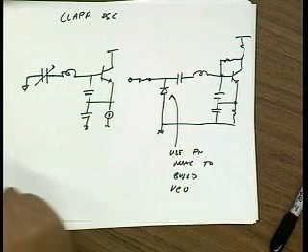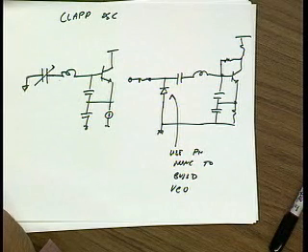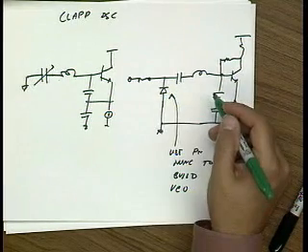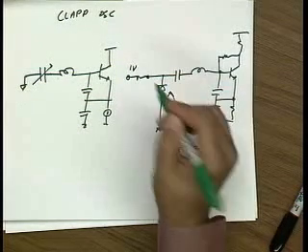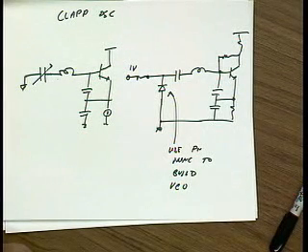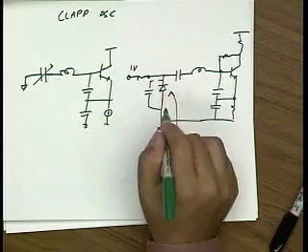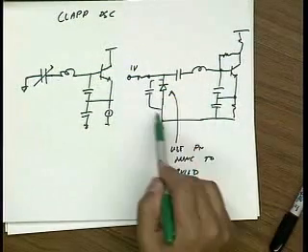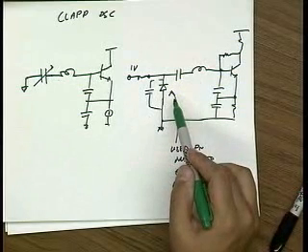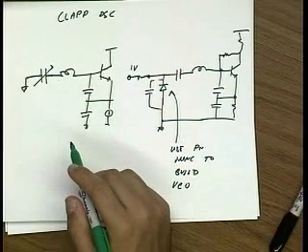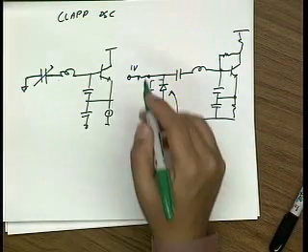Yes. This varactor diode capacitor, isn't this shorted at AC when the voltage is DC across the diode? So this is reverse biased, right? One end is ground, the other end is DC voltage. Let's say I put this at 1 volt. So at omega naught, it's shorted AC-wise, isn't it? No, this has a value. The PN junction reverse bias capacitance is on the order of these caps, so it becomes part of the tank. What do you mean by shorted? Well, 1 volt is AC ground. No, it's not zero volts. Oh yeah, I see your question.